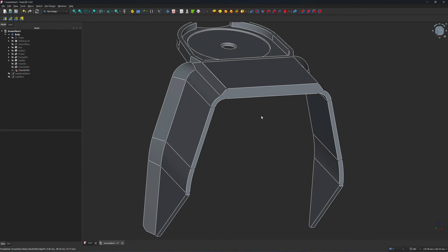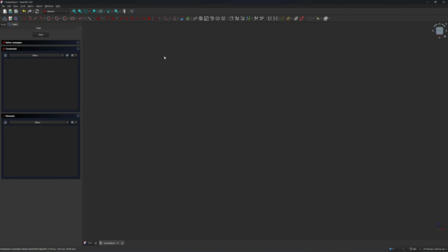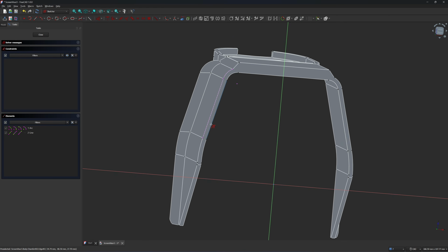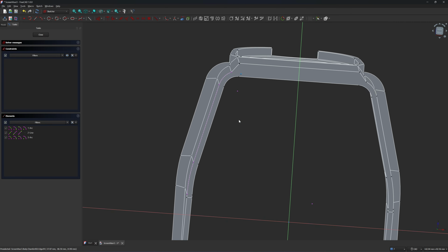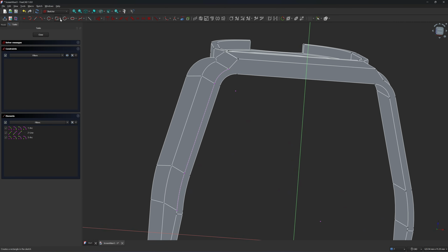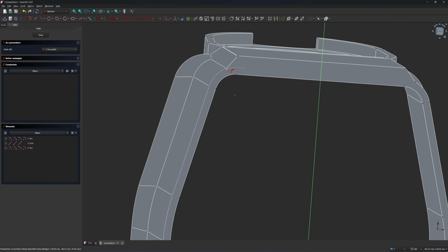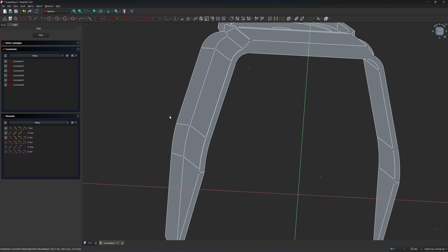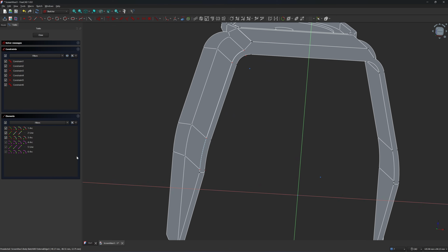Okay, next I'm going to make a base for printing. Click on this plane. Click on sketch. Create external geometry. Okay, I only need the 3 here. And then I'm going to trace the line. Okay, the last one. Okay, next I'm going to offset this line. For that, I'm going to delete the projected line first. So I don't want to select it. Click on delete. Yeah, I think they have a problem with the selection.